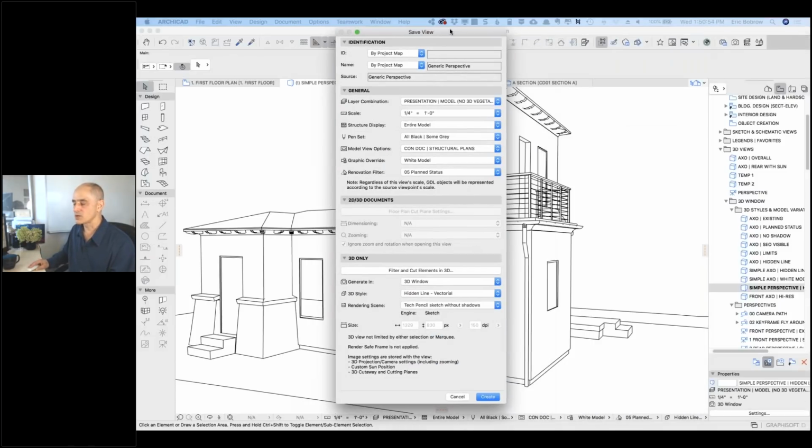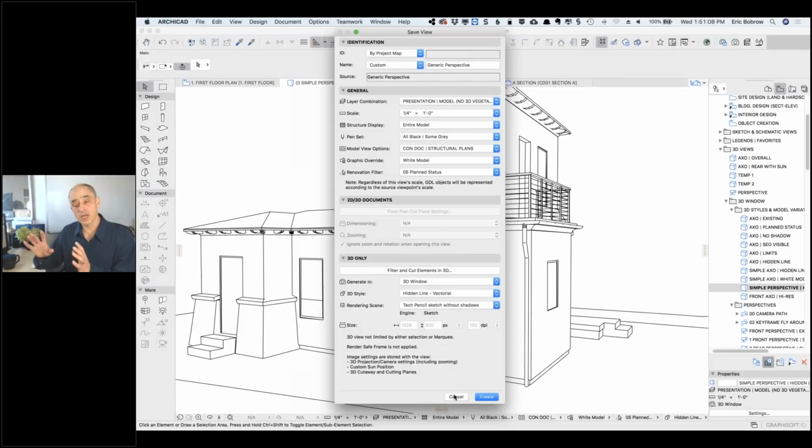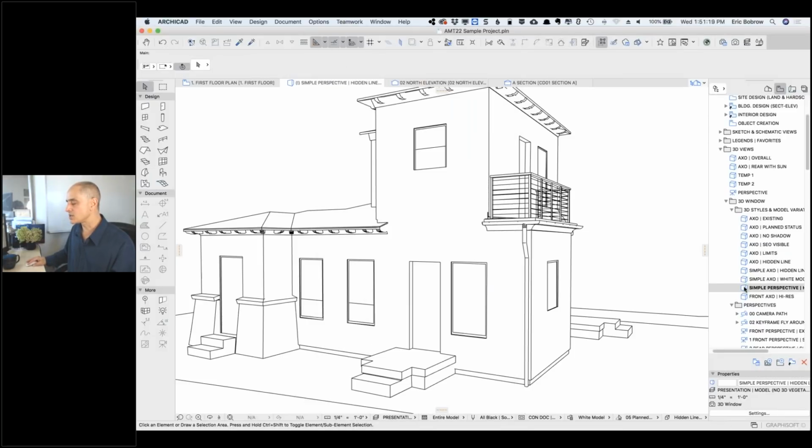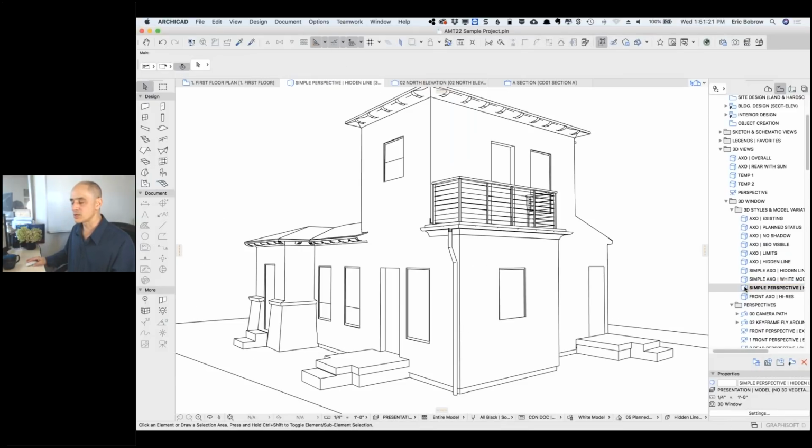So we can say that we want to save this view, and then we can give it a name, a custom name here, whatever we want. That's how these were named. And it'll save all of the context, including the 3D positions. So when you have something, say, hey, this is a nice view, just save it, because then it's so easy just to have it at hand. Now I'm not going to add it here. I think we don't need that. And if I double click on this, it'll go back to the earlier viewing position.